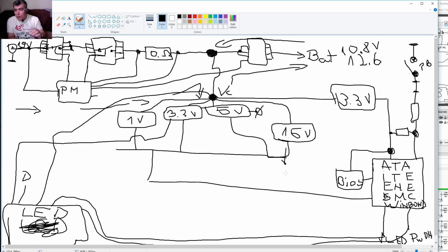So you have to understand how this thing works. After this chip does the auto test, yeah, the startup chip, it will power up the screen. If something in your laptop is failing the test in the startup procedure, you know, when you press the power button, then they will not give the signals on this pin. So on this pin I should have 3.3 if everything is fine. 3.3 volts.